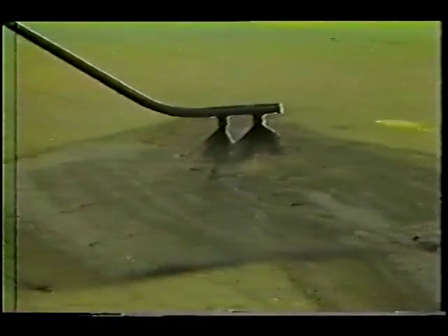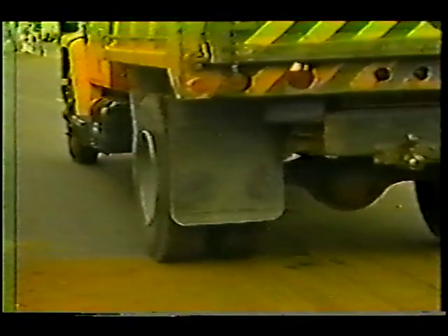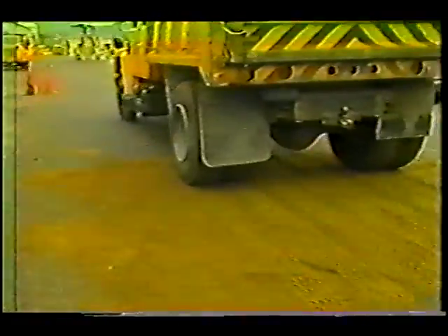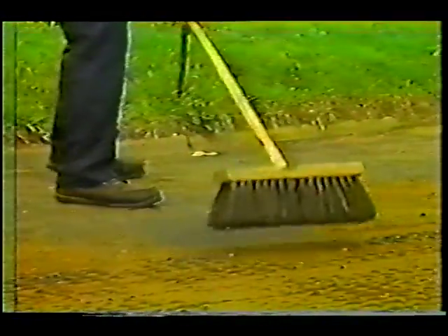Step 4. Apply the liquid asphalt over the cracked area. The asphalt should cover the repair surface in a light coat. Step 5. Spread the cover aggregate. Cast it evenly over the entire repair surface in a single layer. Step 6. Roll the aggregate. This will make the aggregate particles stay in place. Step 7. Clean the work site. Sweep and properly dispose of any loose aggregate.